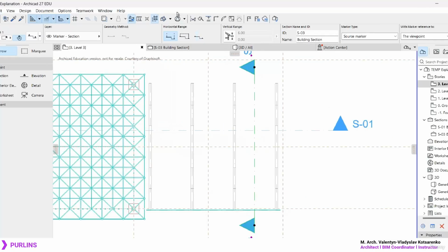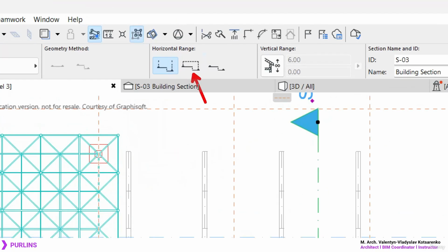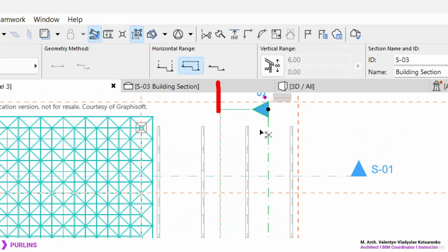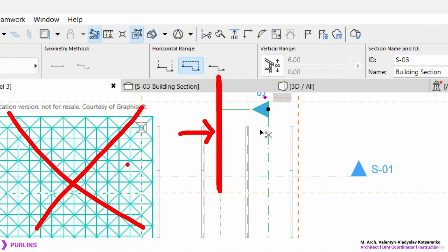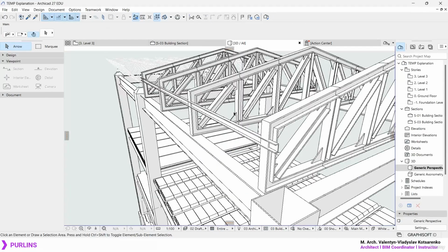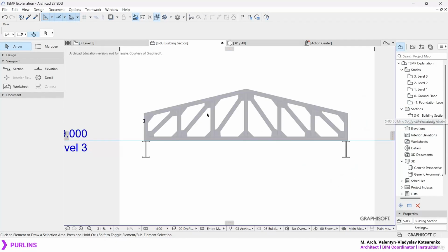Select your section view and activate the limited type of representation. Let's activate this one. So yeah, it's going to be limited to until this line over here. So we don't visualize the three-dimensional slab we got before, but only what we require for this example.